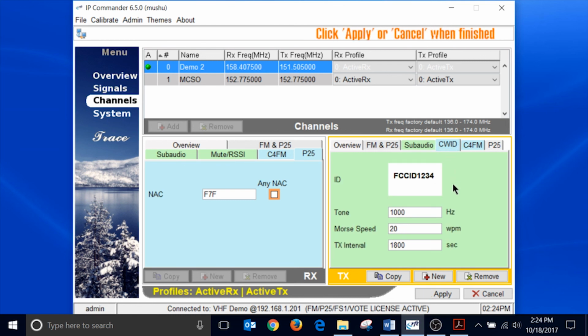CWID will also only show up if it's in the signal screen. This is the field where you'd put in your FCC call sign. You can use whatever frequency you want. I like 1000 hertz. Morse code speed of 20 words per minute, and 18,000 seconds, which is 30 minutes between IDs.